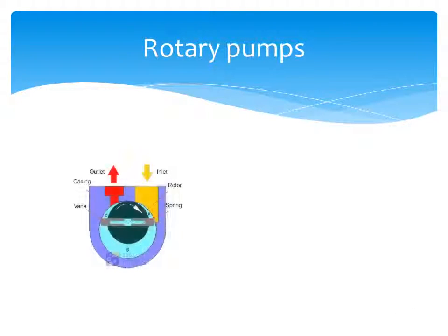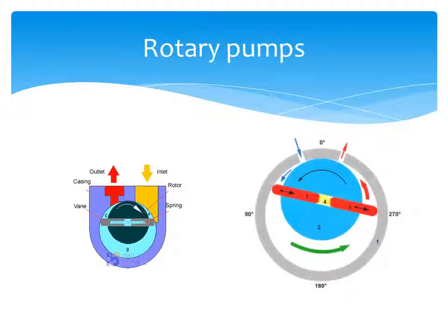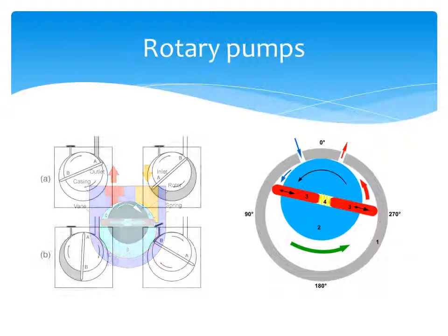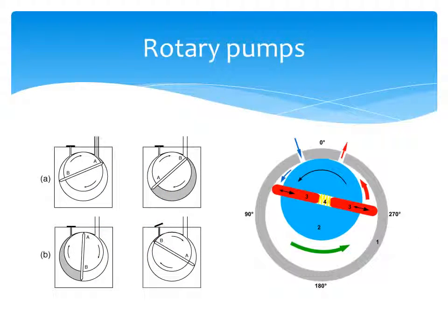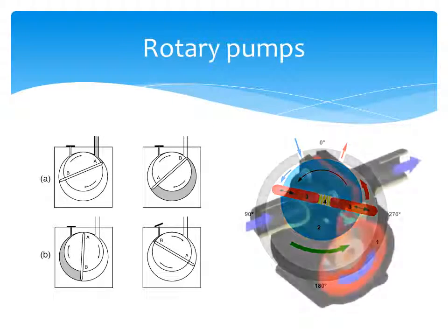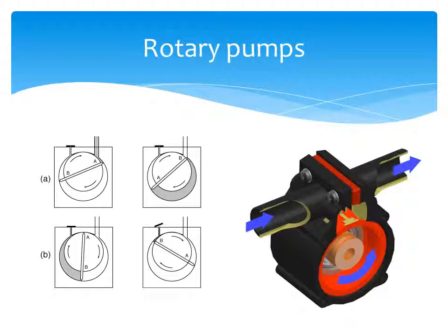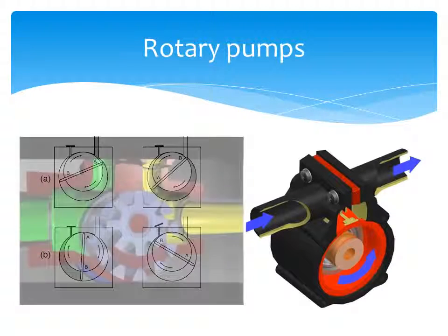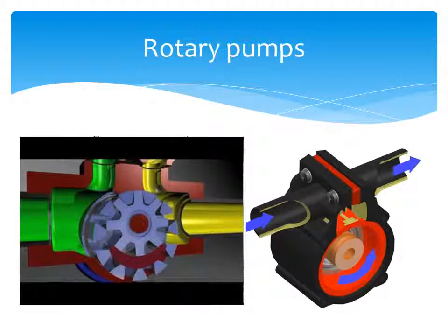Rotary pumps are defined as being vane, piston, flexible member, lobe, gear, circumferential piston, or screw pumps. In all of the rotary designs, the chamber is created progressively through rotation of the drive shaft. There may be one or more chambers opened per revolution depending on the design. The chambers are sealed off from suction by close clearance between the rotor and the housing, or by close clearance between intermeshing rotors. Rotation of the shaft moves the chamber along the bore or housing towards discharge. The chamber is displaced to discharge by rotation. The release to discharge progresses with rotation, as the volume is expelled, so that the flow is typically pulsation-free.